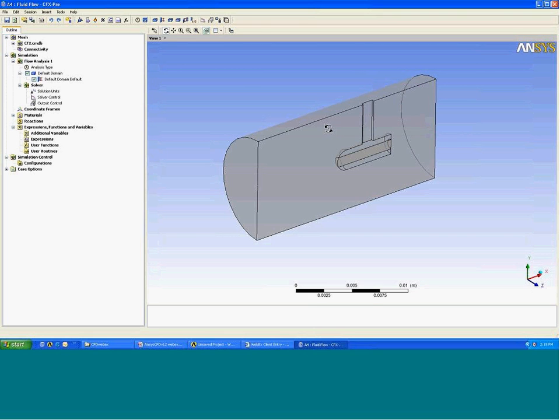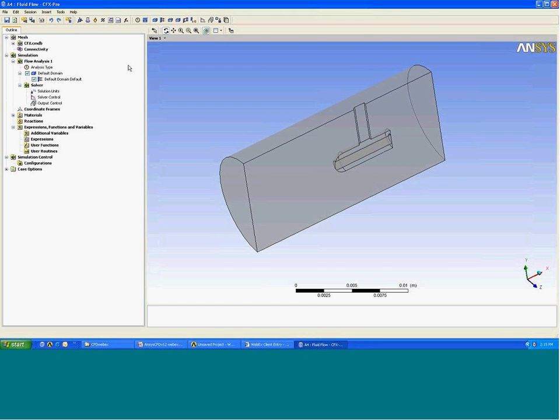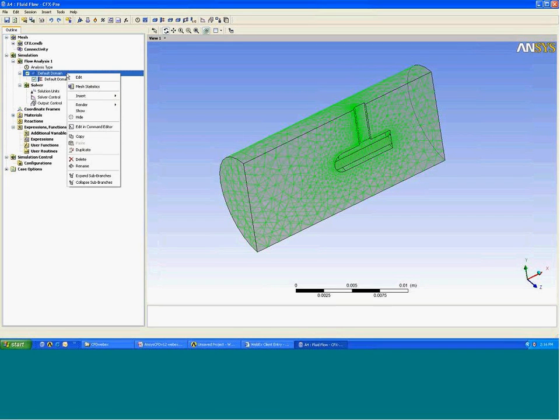We're going to define the analysis for this probe calculation, as outlined in the PowerPoint file. We're going to set up airflow at 30 meters per second going through this probe, and we're going to see pressure drop, velocity contours, pressure variations across the probe, and average pressure on the probe surface, and so forth. Right? So first of all, we want to define what we're solving. And in the setup, it creates an automatic default domain.